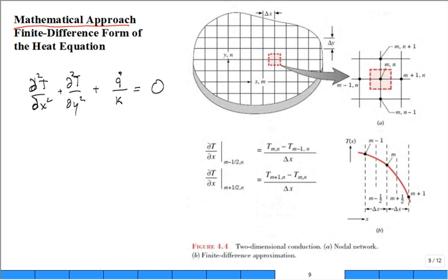What they do is they say, what we're going to do is introduce a grid, and then we're going to have this location. And what we'll do is approximate that x derivative, go back to numerical methods. Temperature minus 2 the temperature plus the temperature, divided by delta x squared. Now it's just, okay, what syntax do we have for our locations? I used the i and j just a minute ago, right? The book is using the m's and the n's. Can you see that? m and n. So let's stay with the book.